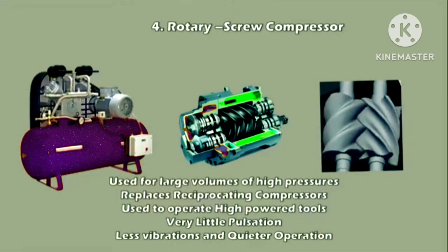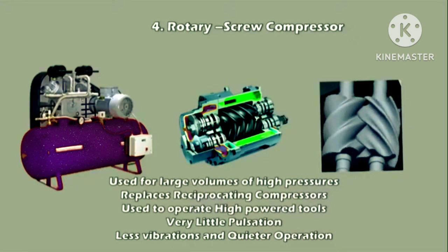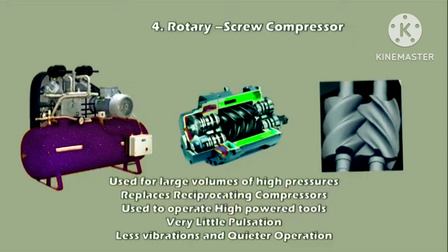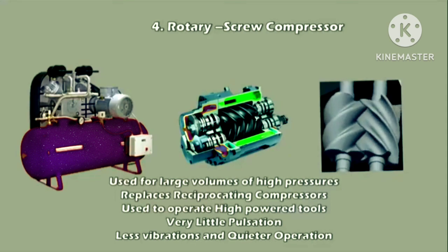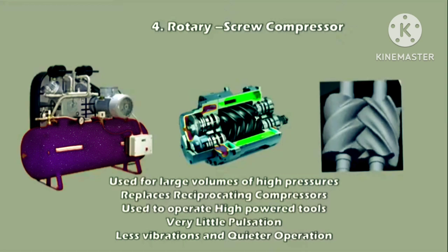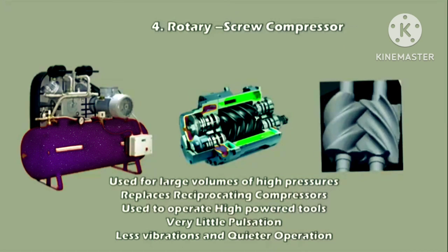The gas compression process of a rotary screw is a continuous sweeping motion, so there is very little pulsation or surging of flow, as occurs with piston compressors. This also allows screw compressors to be significantly quieter and produce much less vibration than piston compressors, even at large sizes, and produces some benefits in efficiency.